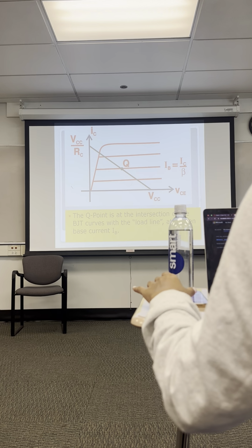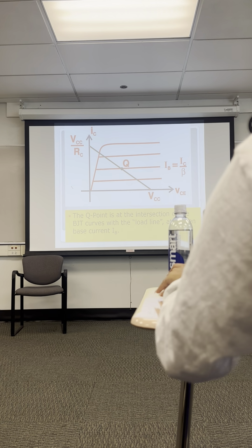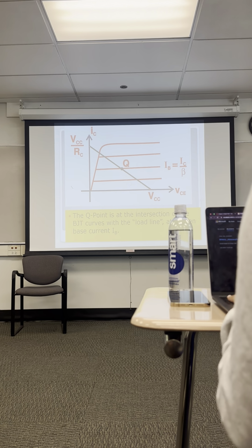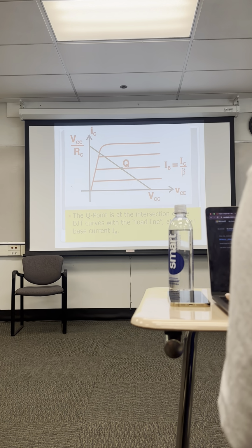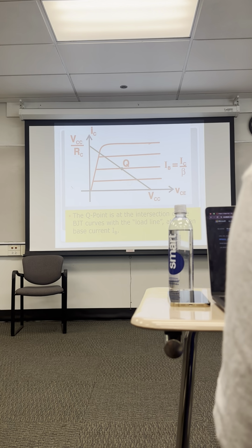One end of it is connected directly to the battery, and the other part is connected to the battery over the collector resistor. So now what you're basically doing is limiting your Q points to just a small set of parameters. So you no longer have to arbitrarily pick Q points that are off this line.